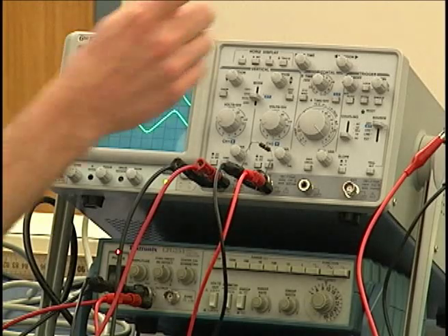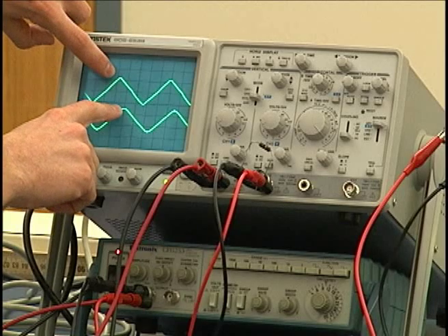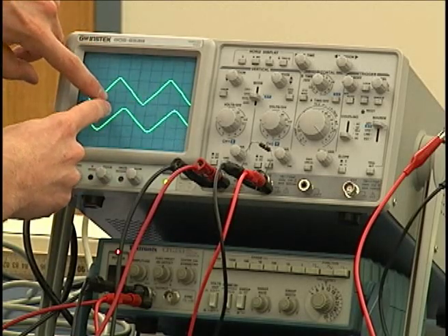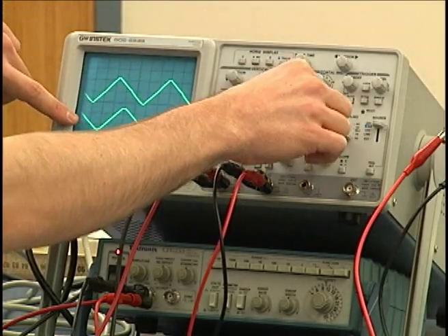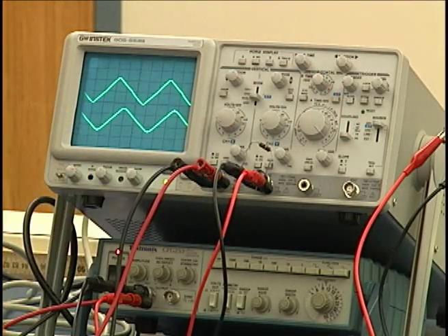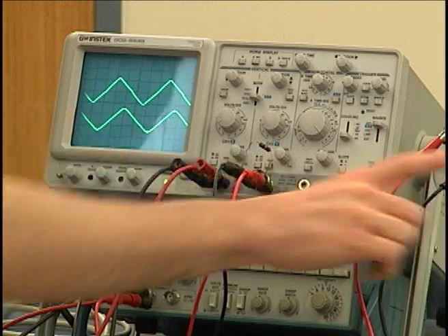So you know the distance because it's written right on there, and you know the time because you can measure this directly from the oscilloscope. Remember, this is going to be the time axis, so you just measure the number of squares from here to here, use your time setting, which is controllable right here on your oscilloscope, and then you have your distance and time to put into your velocity equation. One snag to be very careful of is some people like to use the 2d over t that we use for the speed of light in air. Don't do that here because you're just going through one distance, not two.